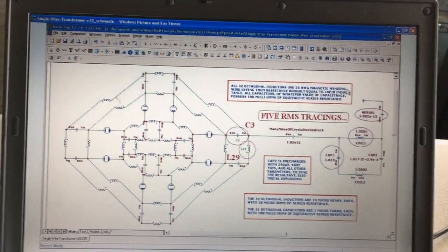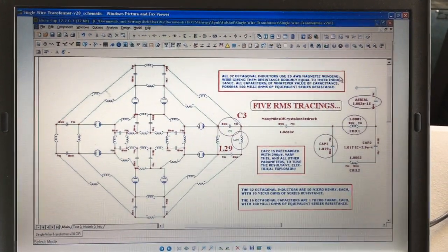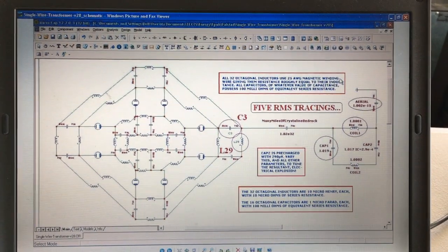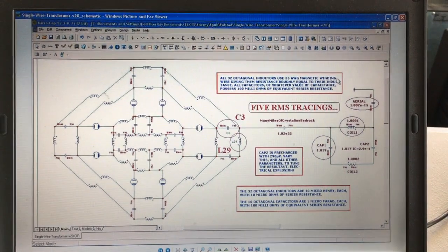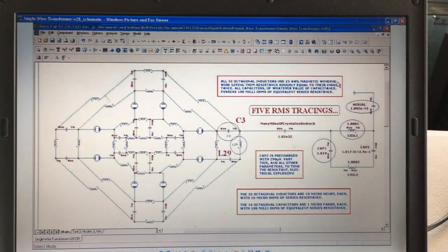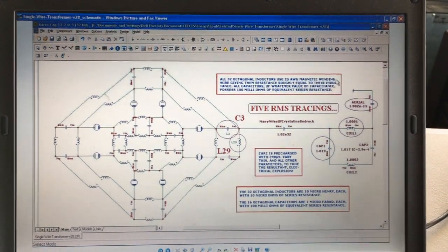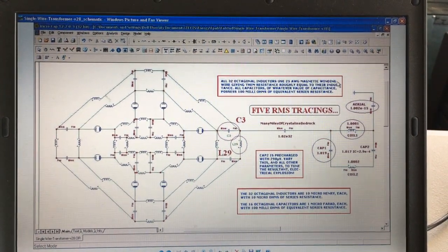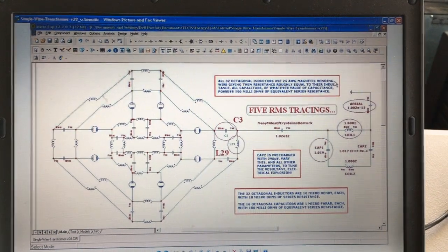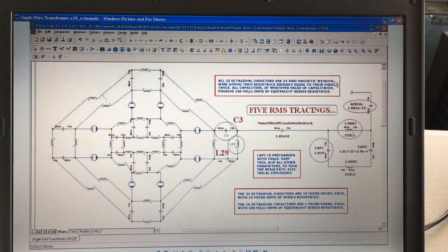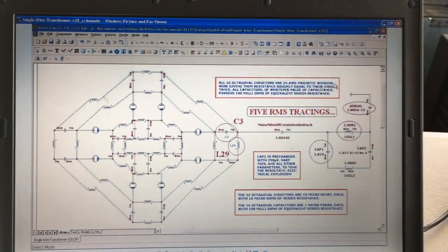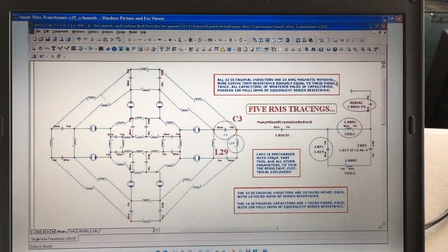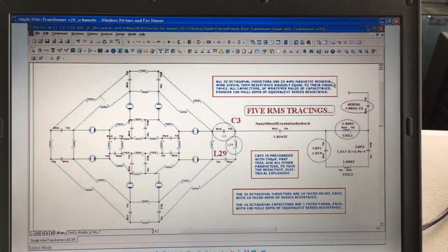And to help me keep track of everything, I make the deviation the same as the numeric value of the label. So if the capacitor is C20, and it's supposed to be 1 microfarad, then I'll reset it to 1.02 microfarads to indicate 20 parts per thousand of a microfarad that I'm deviating it upwards. Keep things simple and straightforward for myself.